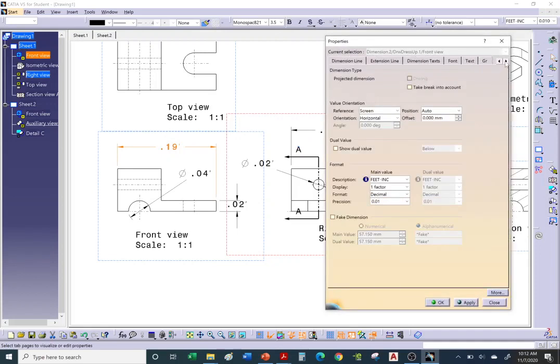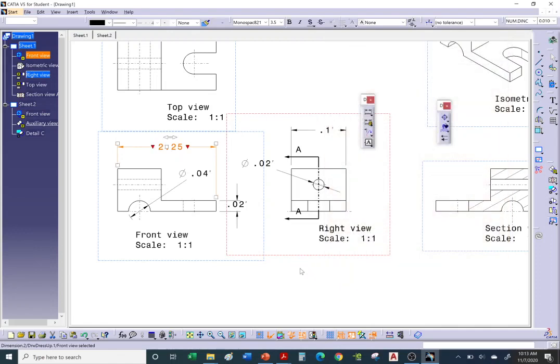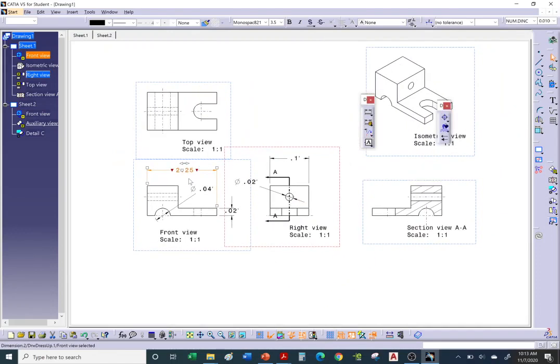And let's see, I'm going to look for units here. Oh, here it is. On the first tab, the value tab, instead of feet inches, hey, I want millimeters. And hit apply and keep an eye on your screen. 3, 2, 1, apply. So if you want millimeters, there it is, millimeters. If you want to change decimal places, you can do it here in precision. If you want to go to inches, go to the third option, inches, and apply. Okay, so this is 2.25 inches. Okay, so this is the long way of doing it, by doing one at a time.